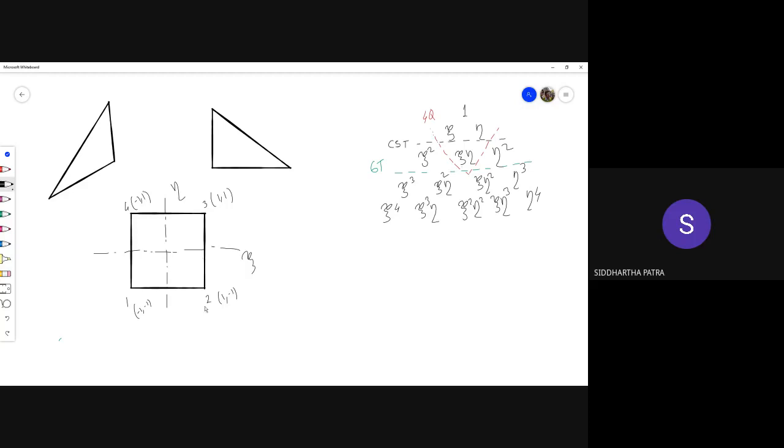You take the shape functions of a linear bar element in the xi direction and multiply them with the similar shape functions in eta, and then you have the shape functions for the four-noded quad element. That is a bilinear shape function, so the four-noded quad element is a bilinear element.